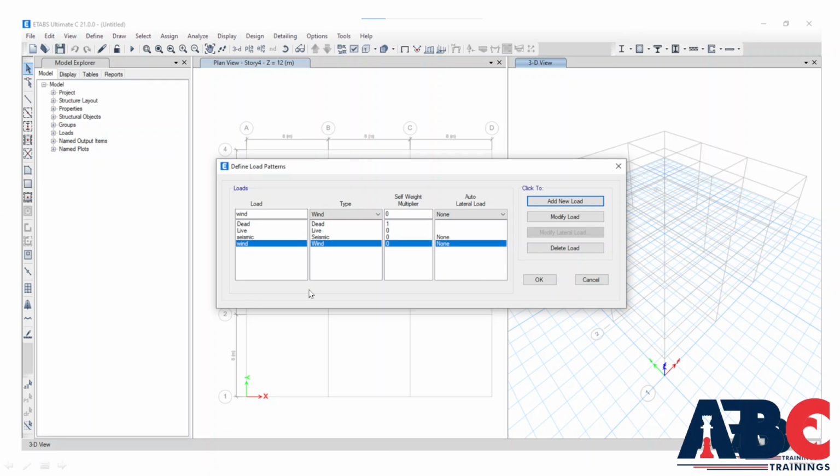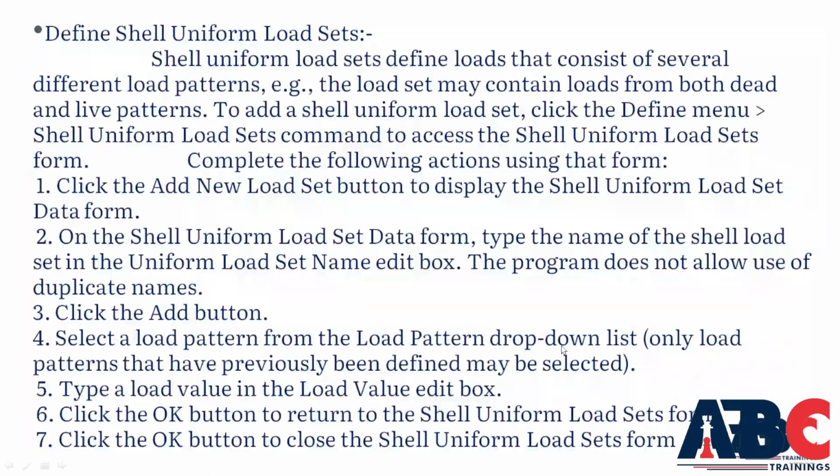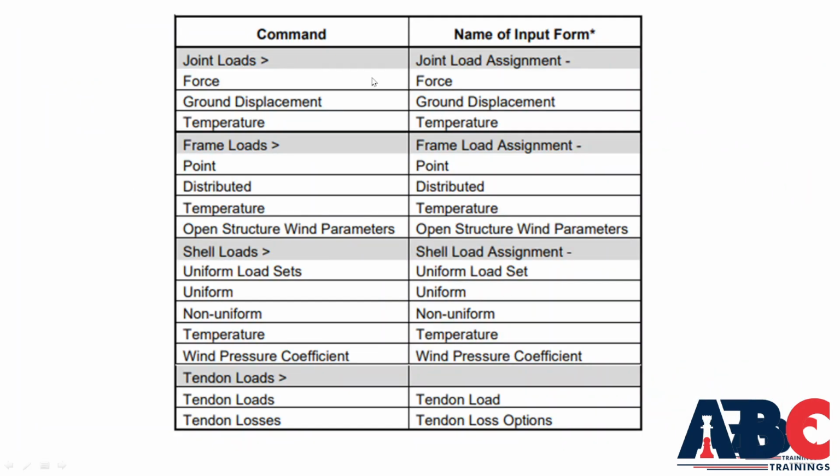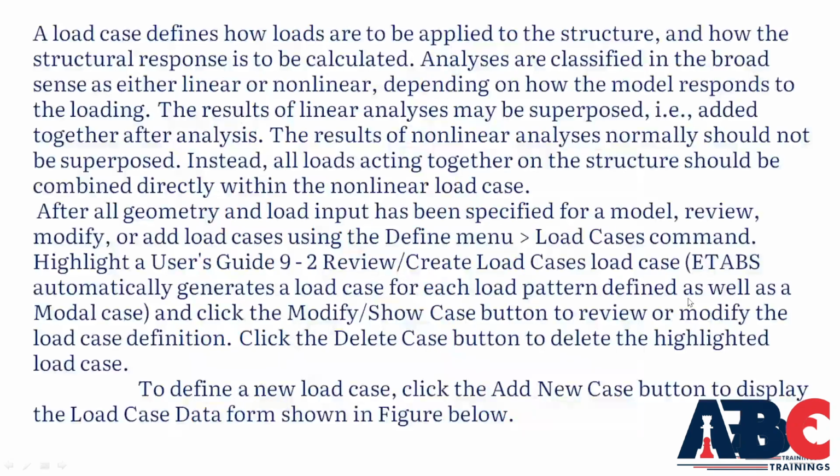This is the define load patterns, which I have already mentioned in my previous video. I will tell you how to give all these loads. Here you can see the commands and the names of input forms. The shell loads are uniform, some non-uniform, temperature, wind loads.